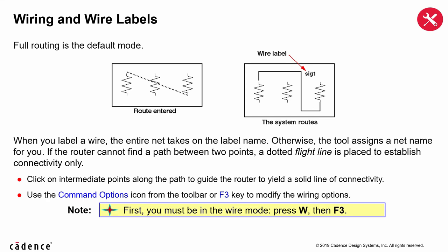Also, always try to label your wires. Labeling wires gives the corresponding net a meaningful name in the simulation results data. Otherwise, nets are system generated. There is some control over the automatically generated names, but these might not be as meaningful as custom names.